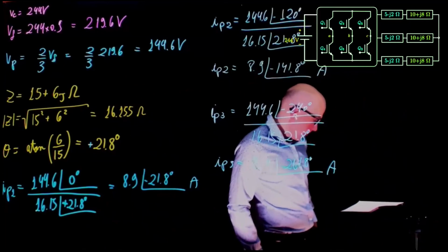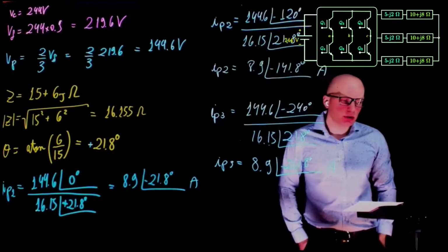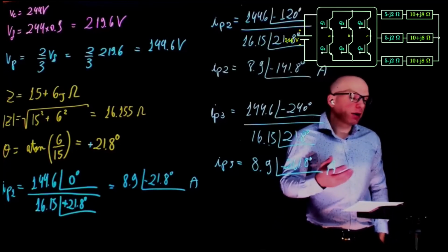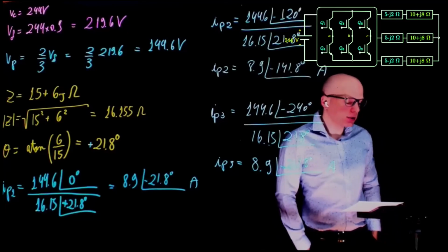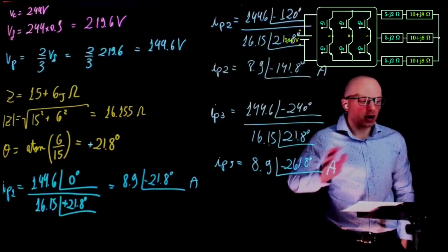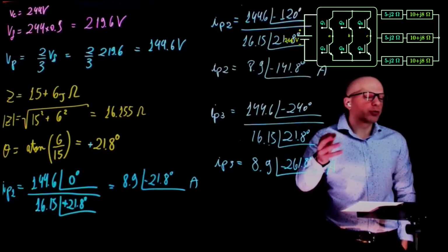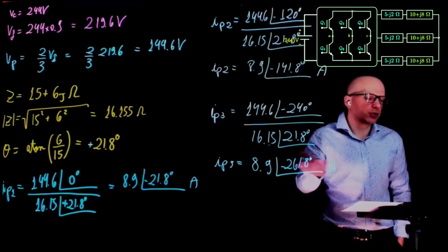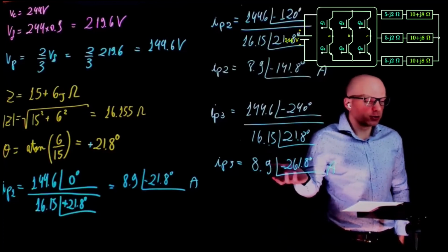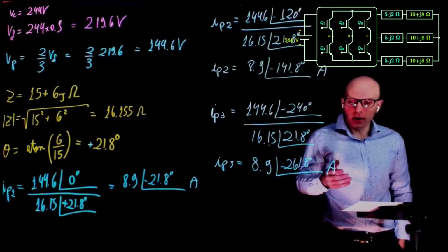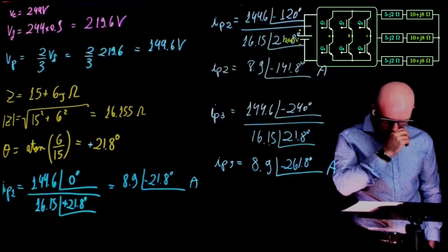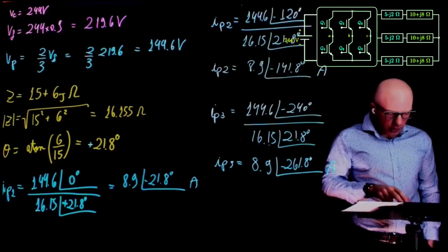I think what is important at this point is to understand how these bridges, these inverters work, and especially for space vector modulation, how later a brushless motor can be controlled using a DC supply. And that is quite interesting. I think this solution to the problem is quite ingenious. I have this vector rotating, which represents the orientation of the magnetic field inside the motor, and then we can beautifully convert that into duty cycles for the operating modes of the three-phase inverters. It is ingenious. And I think that understanding is sufficient. We don't need to complicate this any more than that.